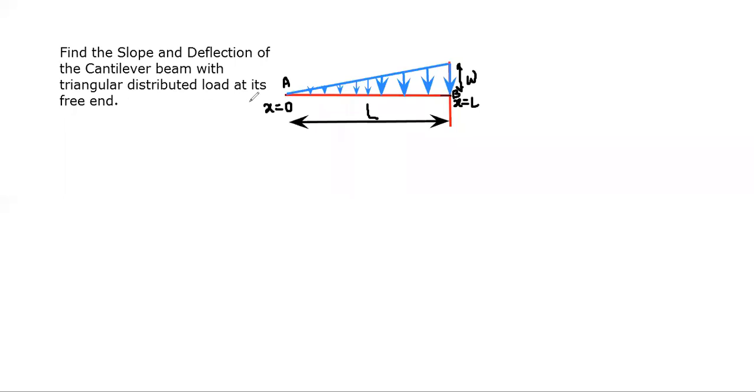method. In order to work with the virtual work method, the first and foremost step is, in the given beam, calculate the bending moment equation. Write down the bending moment equation for the given beam. And we know, in order to write the bending moment equation, we will first of all draw a section. Let's draw a section of the beam, and let's suppose we draw a section over here.